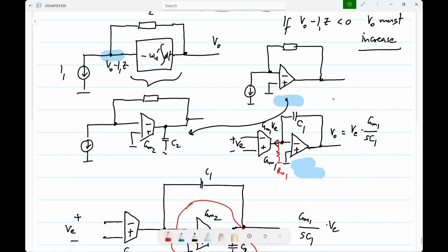Let's look at it with the ideal op-amp. The point is that this RO1 now is across the virtual short. It won't draw any current. So you don't have that earlier problem anymore. Because earlier, if you had any output voltage, there would be that voltage across RO1 which was drawing current, which had to be supplied by GM1. Now the voltage across this is 0. So with DC steady state, the GM doesn't have to supply any current. So that means its input voltage can be 0.